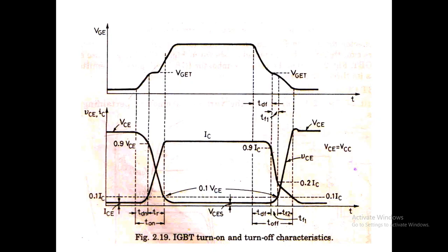The time required for the current to increase from the leakage current to 10 percentage of IC is the turn on delay time.